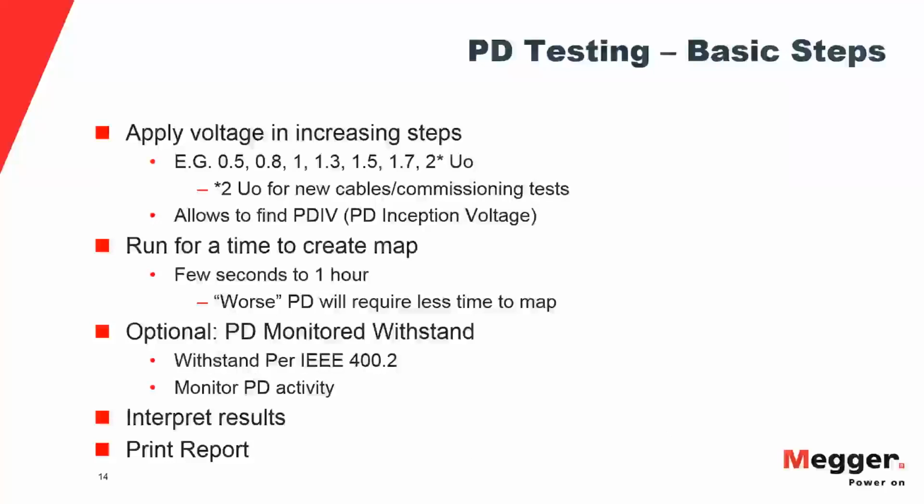There is some information given in IEEE 400.3, but there's no real standard available for partial discharge testing in the IEEE world. There's been a lot of work done in the IEC world. It's been well known for many years there, and they have a little bit more information in the IEC standards.